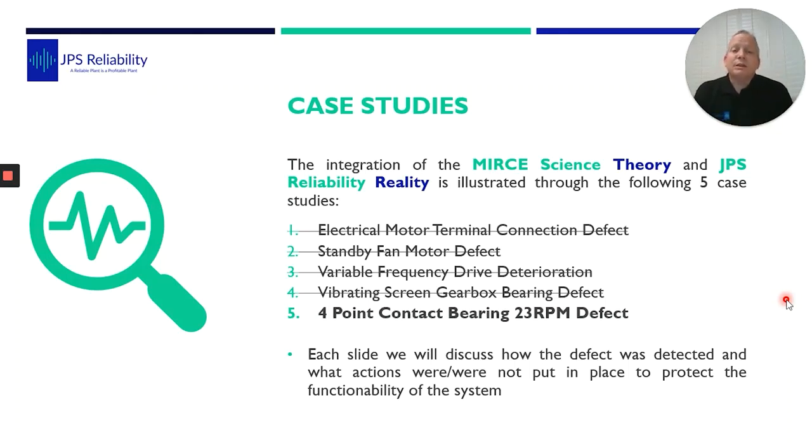Number 4 was a vibrating screen gearbox. Again, another great case study. This one was showing us that if you use the correct sampling, the correct techniques, you can measure an in-race defect even in the harshest environments of a shaking screen.